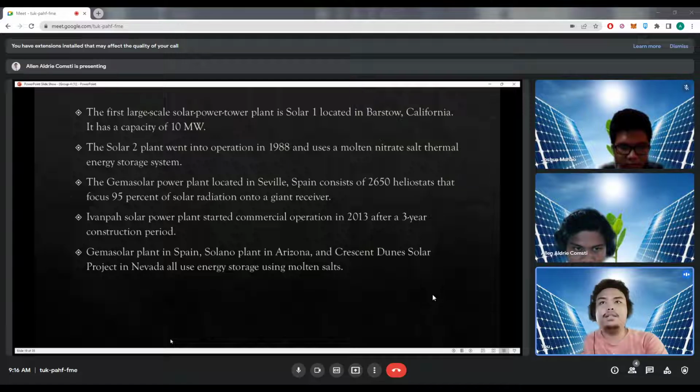Molten salt tanks are heated by concentrated solar heat reaching temperatures above 500 degrees Celsius. Water runs through the molten salt tanks in which it is boiled and superheated. The resulting steam is directed into turbines to produce power. Steam leaving the turbine is condensed and pumped back to the molten salt tanks to repeat the heat engine cycle.